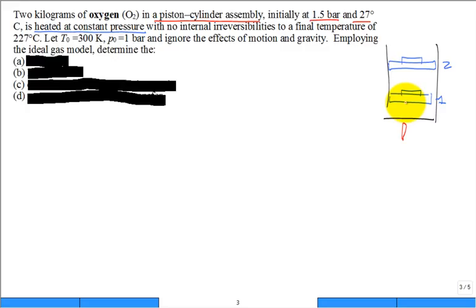And they say, the piston's at a higher elevation. It has to be a higher pressure. I get about a third of them will say that. 2/3 will say, nah, you didn't trip me up. I took statics. I could draw a free body diagram of that piston, isolate it. When I do, I have the weight coming down, I have atmospheric pressure coming down, and I have the pressure below pushing up. And guess what? The elevation of the piston doesn't come into play. And so the pressure at 1, I can conclude with confidence, is equal to the pressure at 2.